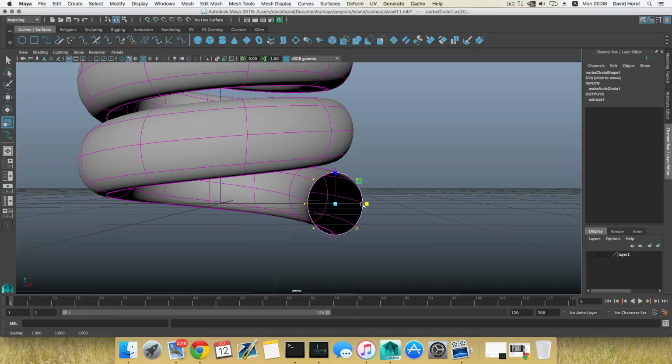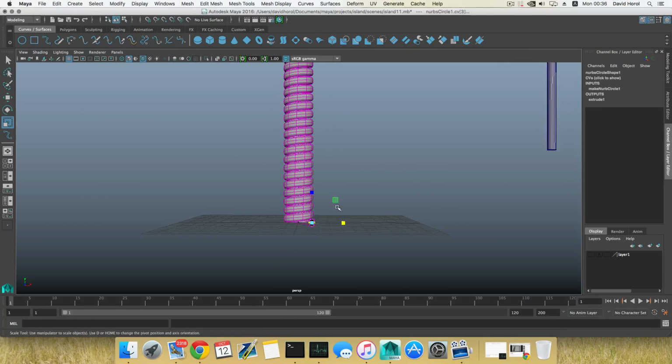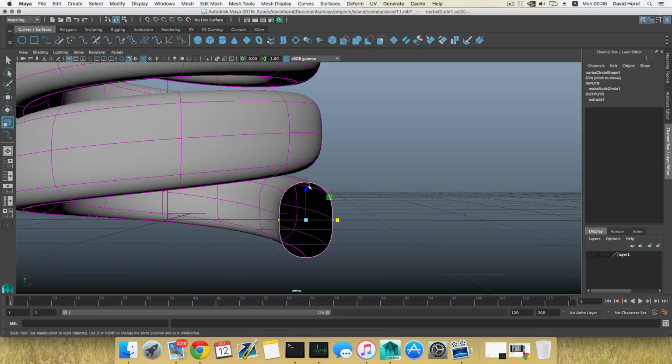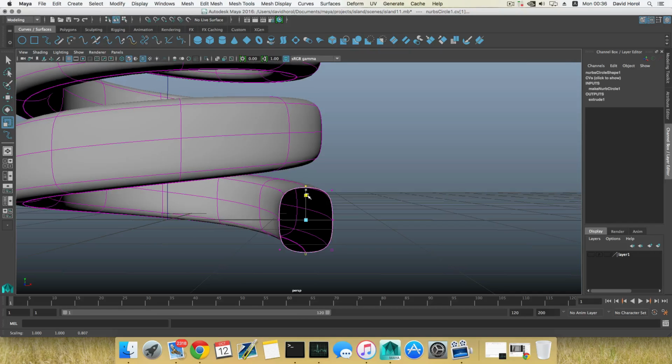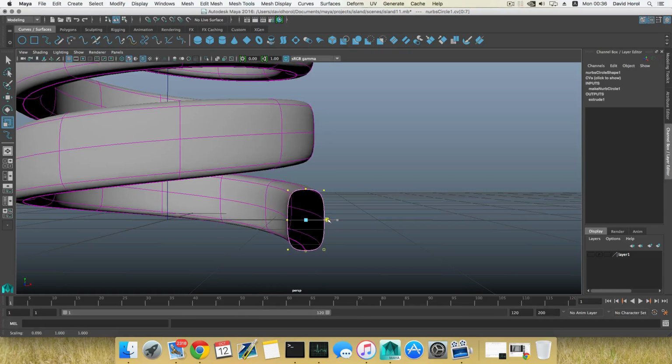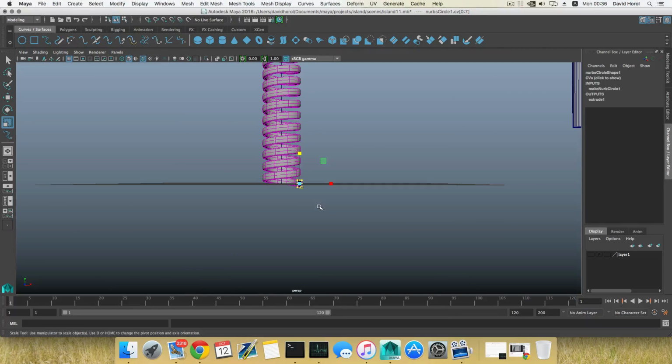And you can grab these 2, squeeze it, like so, and you can see it turns a little bit cubic that way, the entire coil. Okay, and you can grab these two, maybe squeeze them also, like so. Grab these all, squeeze them, squish them, and press F8.